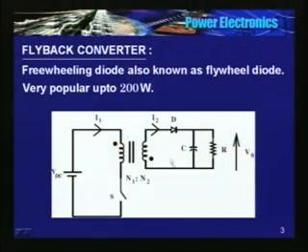So this power supply is known as flyback converter. Circuit topology is same as the previous one. Only thing is I have replaced the voltage source of V2 by a parallel combination of C and R. C is equivalent to the output capacitor, which maintains a constant voltage at the output, a load is connected, a variable R.